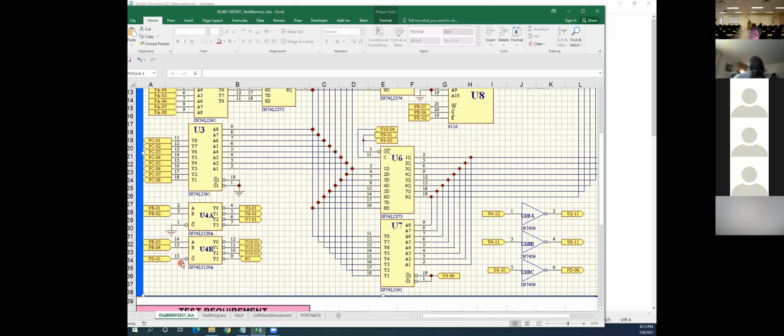So when you apply pin 15 as 0, this pin 12 goes low and the output goes high. Then you apply pin 15 high, and now this output goes low. You want to create one positive pulse. That means when it goes high, they lock it. After that, we want to lock it, no more.